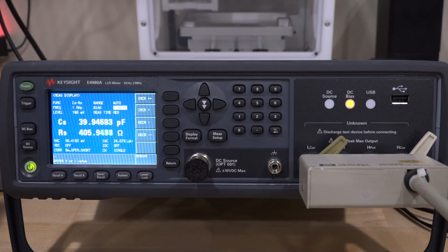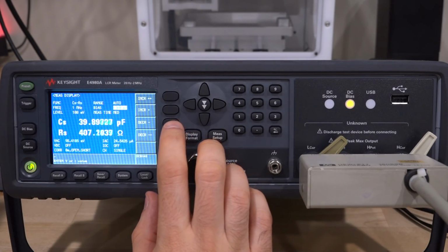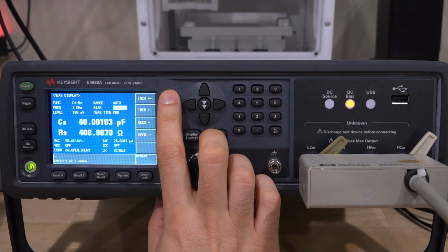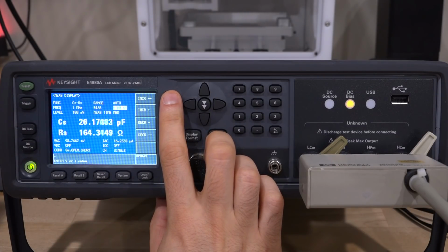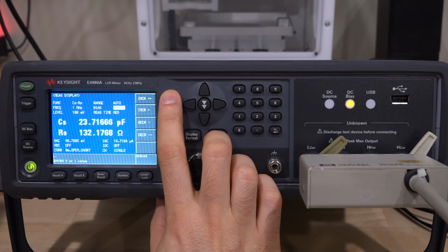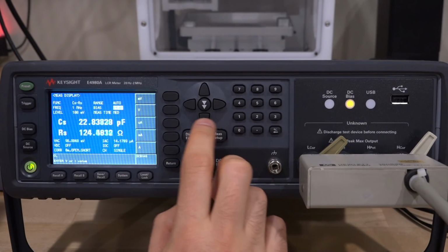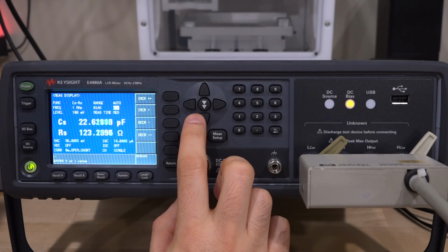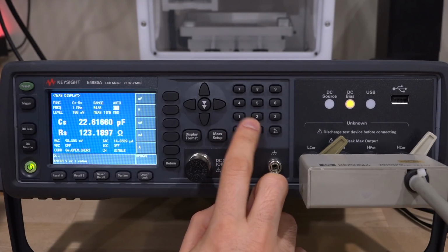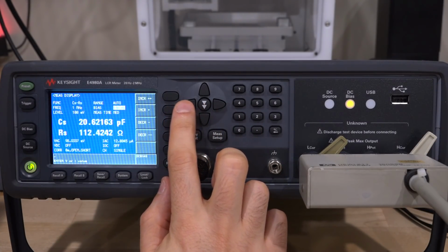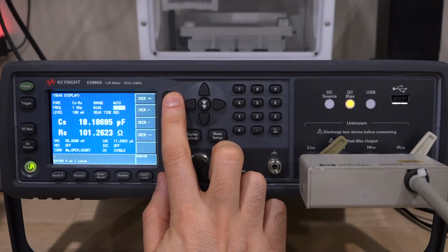Now look what happens when I change the voltage. So we're going to go from minus 200 millivolts towards 0. Minus 100, you can see the capacitance already changed quite a bit. If I keep going down, eventually we're going to hit 0. Just enter 0 here. There you go, 22. Now I can go in the positive direction. So let's say 0.1 volt. You can see it dropped again, and again, and again.